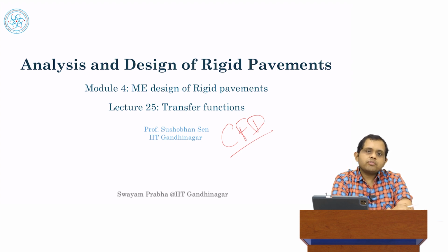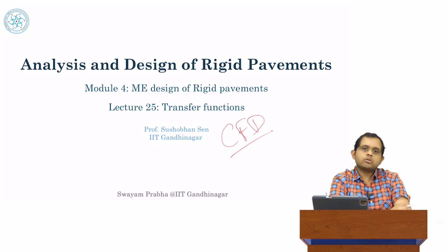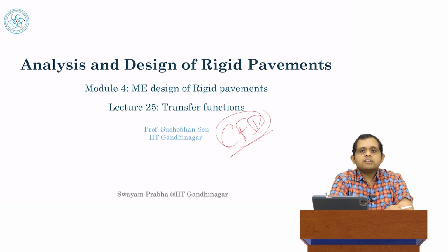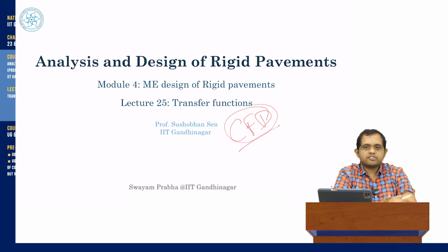That is then when, if we want to actually model a crack or faulting or any other distress on the pavement, then we give up on the idea of doing it mechanistically because it requires fairly complicated non-linear mechanics. Instead, we take this fatigue damage term and we somehow empirically convert it into cracking or faulting or whatever other term we are interested in.